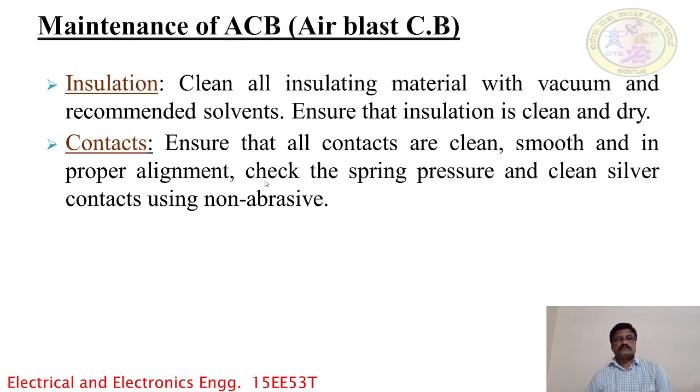And also check the spring pressure and clean silver contacts using non-abrasive material. So the moving as well as the fixed contacts. So the gap variation by the spring pressure. So this pressure of the spring can be checked every scheduled maintenance.